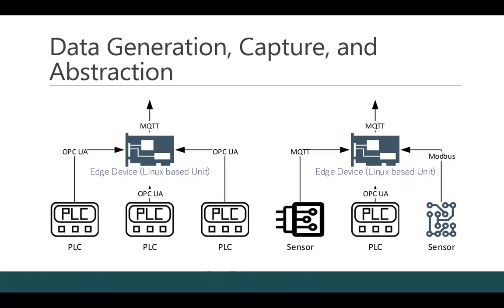Those data connections to devices can be facilitated by OPC UA, MQTT, or proprietary types of protocol. As long as you have the proper driver or software, the data should be able to be read. Edge devices will then be used to abstract or normalize the incoming data so as to present a uniform and structured flow of data to higher levels of the stack.